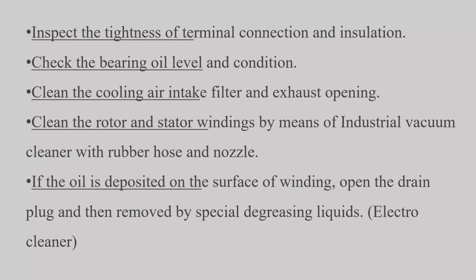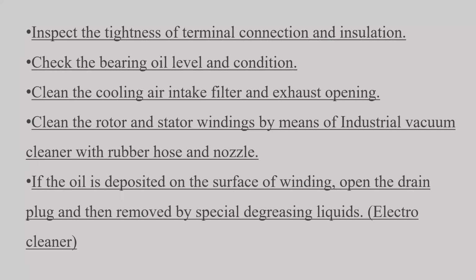Next is to inspect the tightness of the terminal connections and insulation. If they don't have proper tightness, they may vibrate and produce some noise. So they should be properly fitted. We have to check the tightness of the terminals. Check the bearing oil level and condition. Clean the cooling air intake filter and exhaust opening. So the air intake filters and exhaust openings have to be checked.